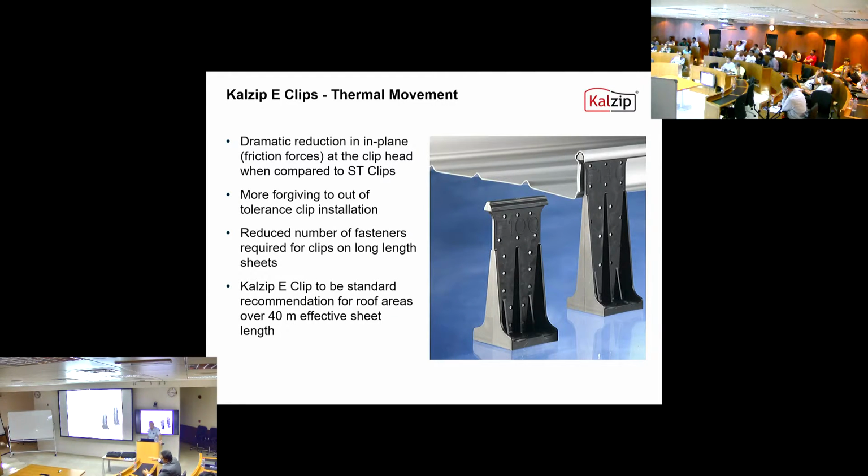Let's say that the panel itself will give crinkling. So over the experience, we designed this clip, one side for the thermal and second side is mainly for the movement, on curved and on long sheet. The steel reinforcement. So the holes are for the injection moulding process to adhere the polyamide to the steel reinforcement. When you are covering the steel with mold, if you keep it all in one without the hole, it will not come and fit properly. It's only the design.